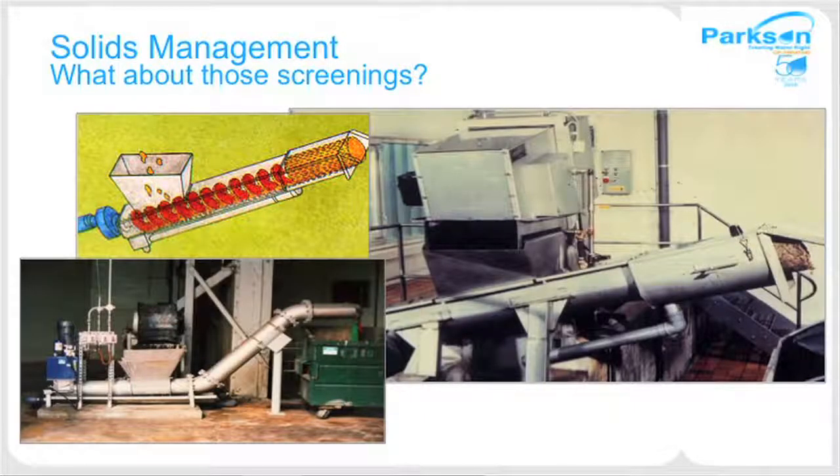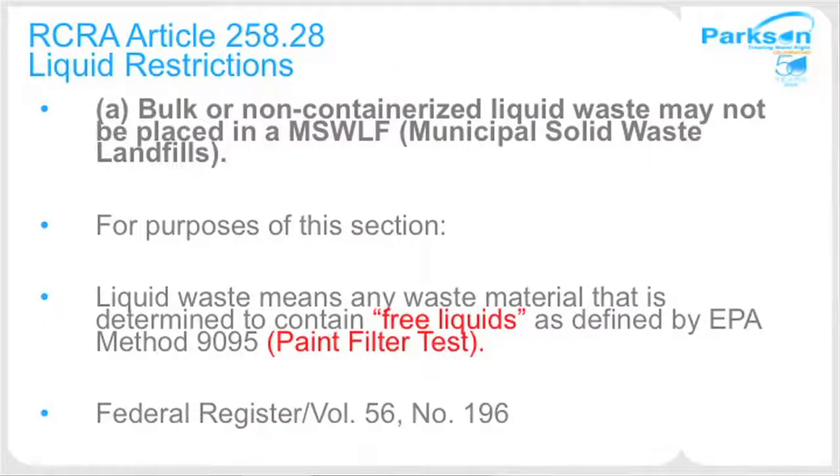Getting into solids management. So what do we do with the solids that are captured by these screens? How do we handle them? And why do we handle them? Municipally, the first thing to look at is the liquid restrictions. If you have free water in your screenings, you cannot take it to landfill. You cannot just discharge it as it is.